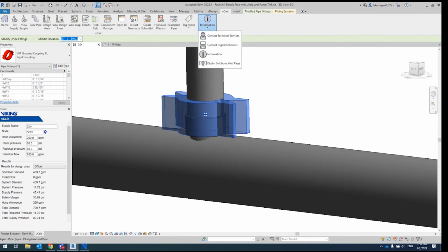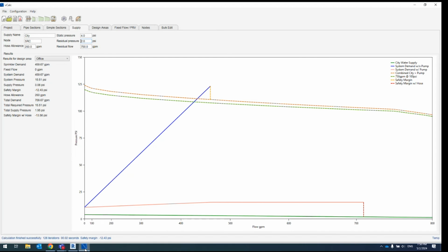So can we use only a fire pump without city water? If you want to do that, you can basically put in a negligible water supply, like what I just showed. You can basically set your city curve to like a 0.2 to 0.1. This is pretty similar to calculating with only a fire pump. It's a negligible contribution from the city.